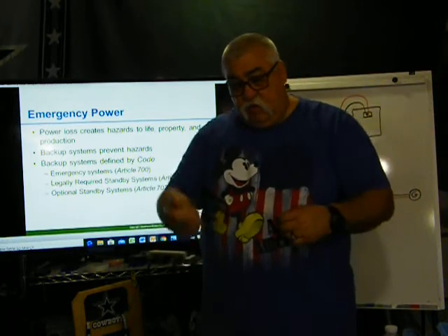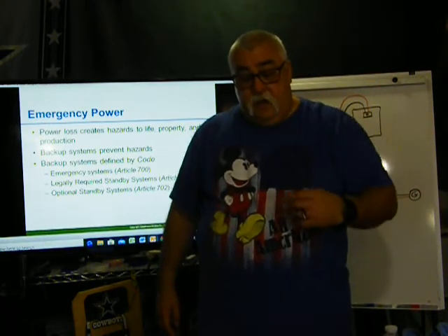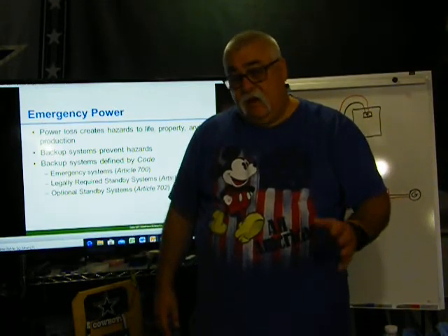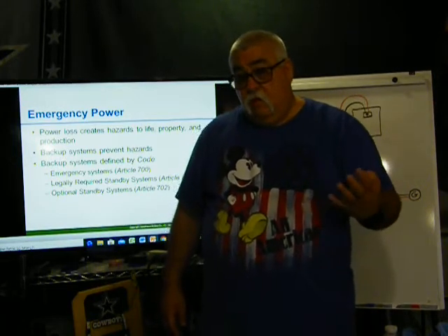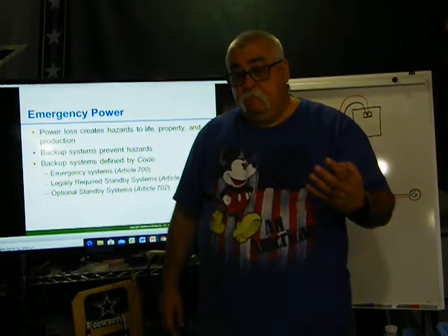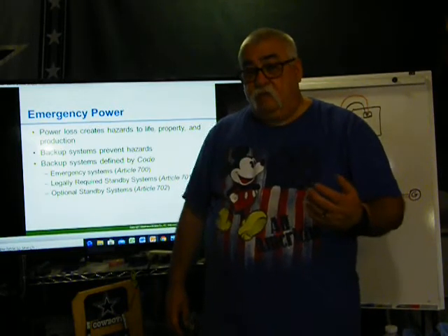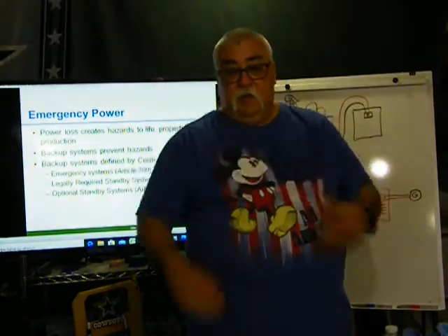And I started taking amp readings. I asked the guy, when is your busiest time? He goes, right now. It was kind of warm, so the air conditioner was running. So I took loads. It was a 400 amp service. They were using 300 of the 400 amps available from the service, single phase. I sat back and I started the calculation.